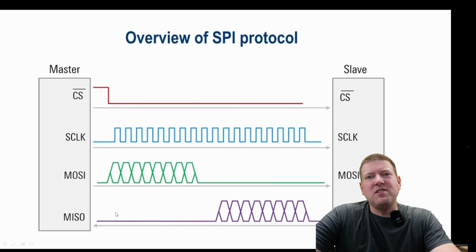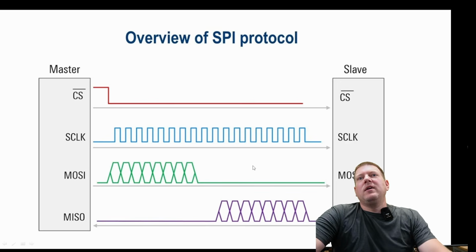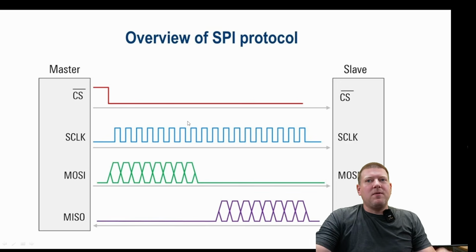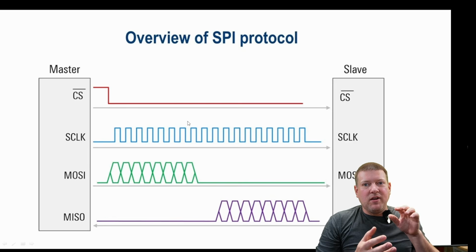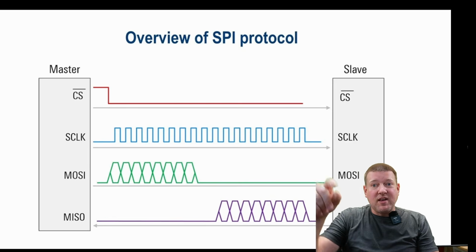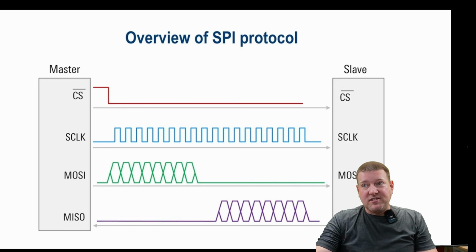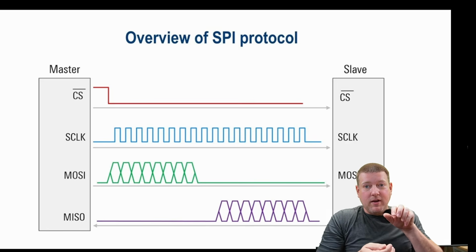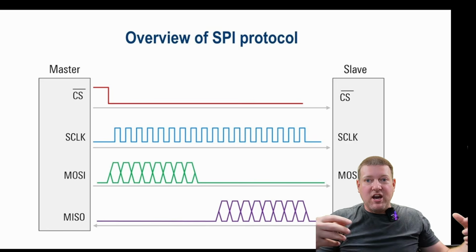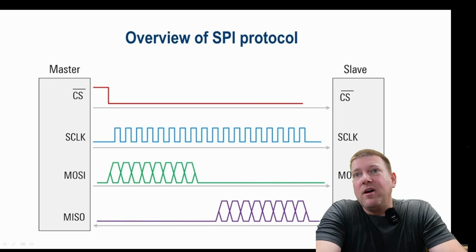and then this is a different look, isn't it? Look at this MOSI and MISO. See how the data is like interwound right there? These are data packets. So it's going to be master out. The master is going to send its data. It's going to be like, here, this is for you. And then remember, the chip select is talking to only one device at that moment. And then that slave is going to be like, here, I have this for you. And they exchange. And that's how it works with those 4.